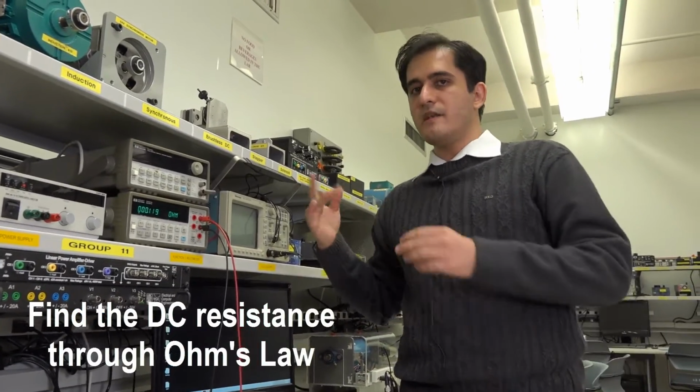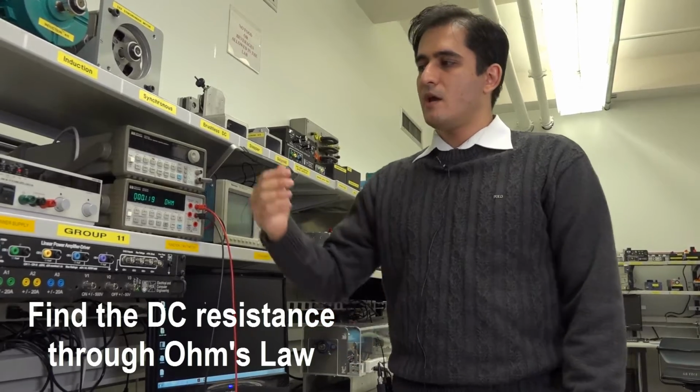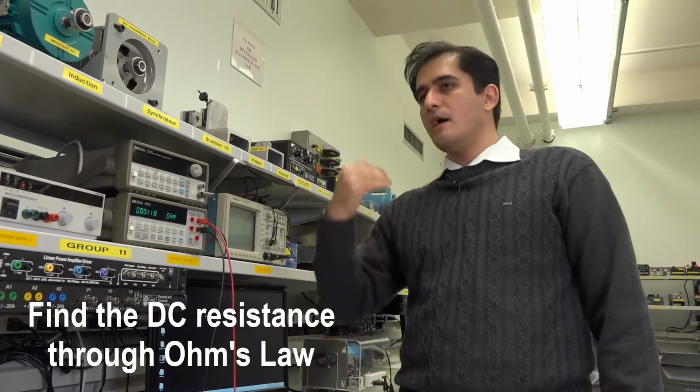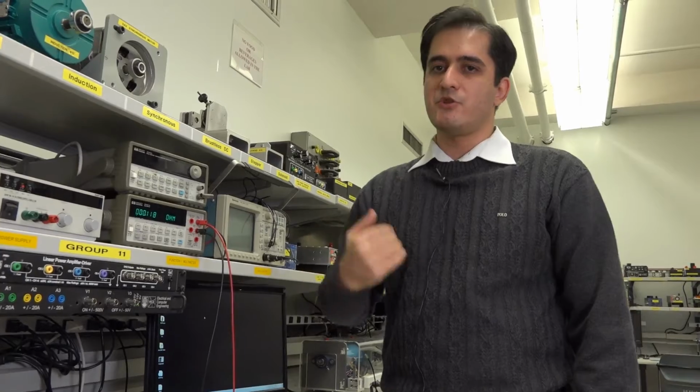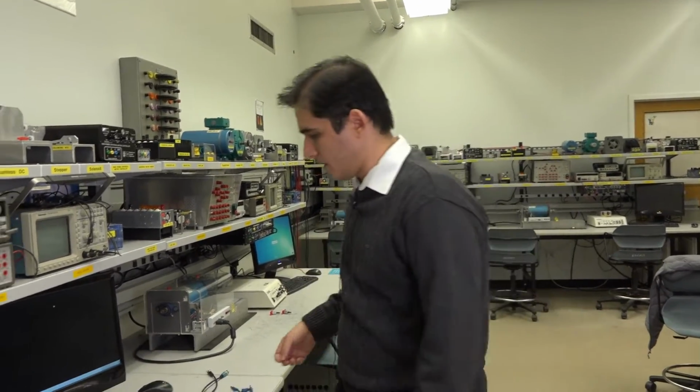Now, there's another way to measure the resistance of a transformer, which is using a DC power supply, applying a very small voltage and measuring the current. The second way to measure the resistance of a transformer's windings is to apply a small amount of voltage to one of its windings and measure the current that is going through the winding.